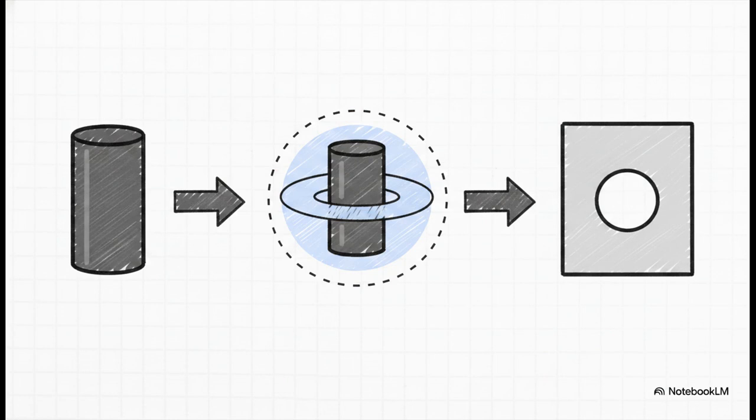And just a super quick note for external features, like a pattern of mounting pins, the logic is exactly the same, but the math just flips. To design your gauge block, you take the maximum diameter of the pin, your MMC, and you add the true position tolerance. That gives you the exact diameter for the holes in your checking fixture.